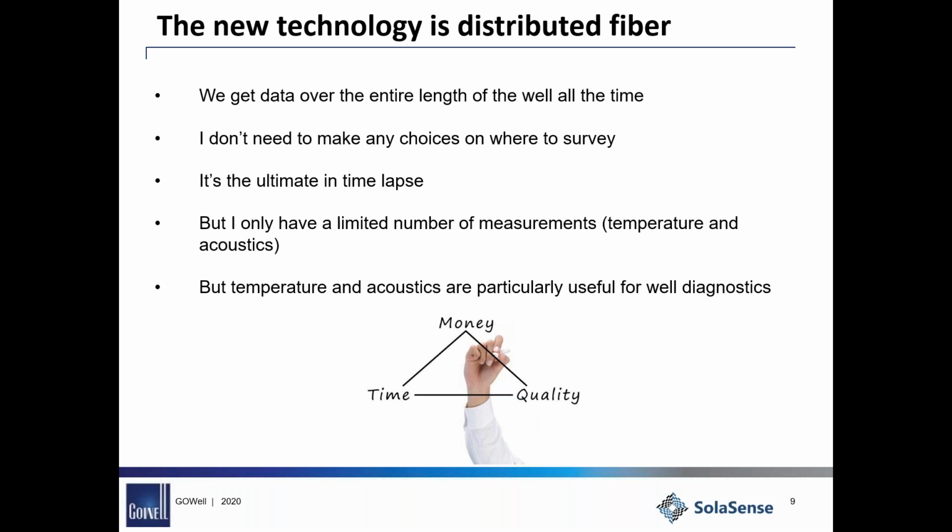However, like all cement data, it's no guarantee of hydraulic isolation. It may tell you the presence of curing cement, but it certainly doesn't tell you anything about the quality of the cement, nor about the bonding or any channels, or many other things. But if all that's required is the presence of cement and the curing process is active, then temperature is okay.